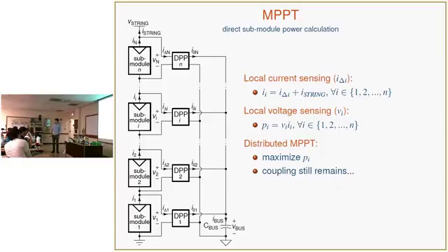Maybe you can arbitrarily choose how many devices are connected to your virtual bus. I think so, though there's probably some limit on it. To build on that, the limit on how many submodules you have is the isolation voltage for the transformer that you use in your DC to DC converter, because as soon as you exceed that, you exceed insulation limits for the transformer. There are limitations for this topology for sure.